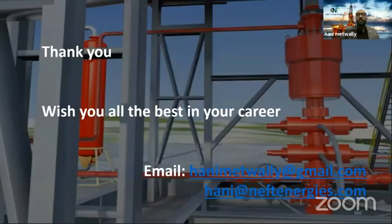But if we have complete loss, we have many options. First one, you can pump lost circulation material and try to bridge the formation. Second one, if we do not succeed in curing the well using lost circulation material, you can pump cement downhole and wait on cement, and then you can try to resume your drilling operation. Anyway, we have many techniques to cure the loss in the hole. So it can be lost circulation material by adding some chemicals, or it can be pumping cement on the bottom, for example.